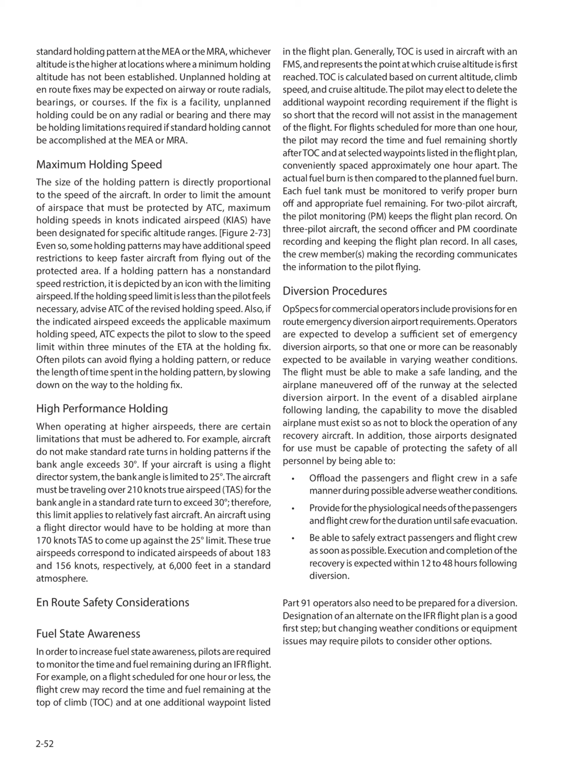Maximum holding speed. The size of the holding pattern is directly proportional to the speed of the aircraft. In order to limit the amount of airspace that must be protected by ATC, maximum holding speeds in knots indicated airspeed, KIAS, have been designated for specific altitude ranges. Figure 273.